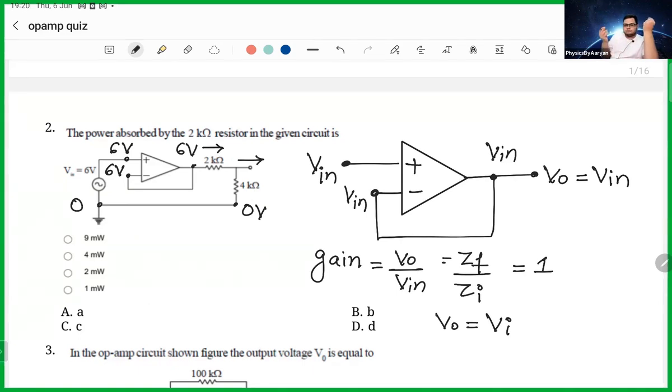The reason being that current cannot go to the open side, right? There is nothing here. Yes, if I connect it with something else, then maybe the current will also go on this side. But for a moment, this is open. So whatever current comes here, the current goes down. So I is here, the same current I is here. So both of them are in series.